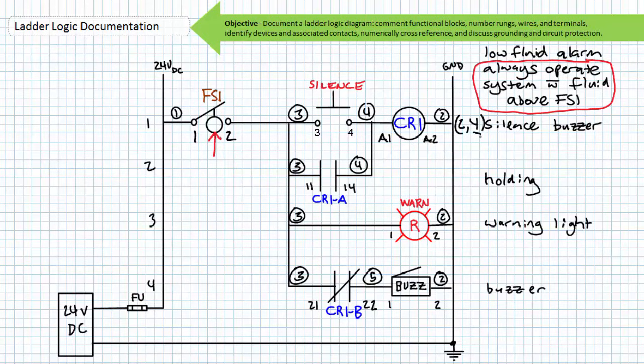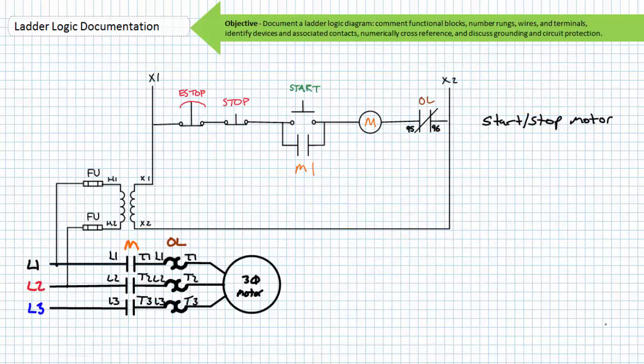If you numerically cross-reference the logical elements in mechanically interlocked switches, your ladder logic diagram should look something like this. Rung 1 has 2, underline 4. Note the underline 4. This means something closes in rung 2 and something opens in rung 4 when rung 1 is energized. Here's example problem 2.